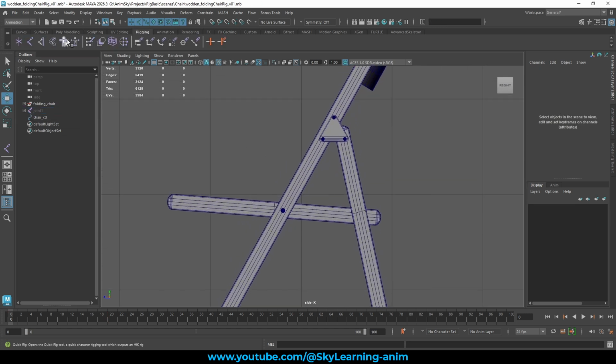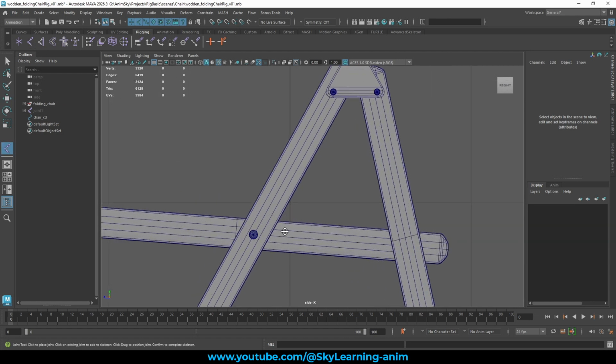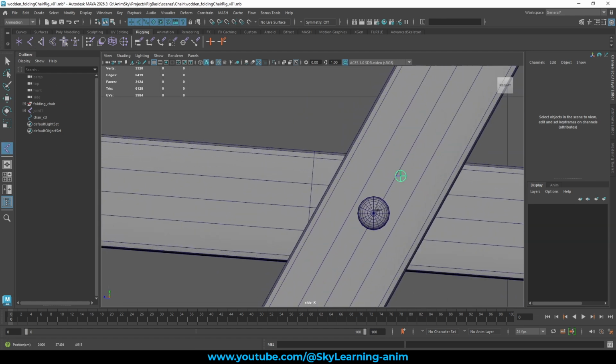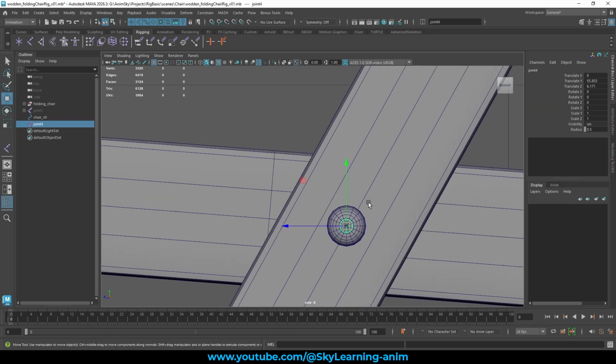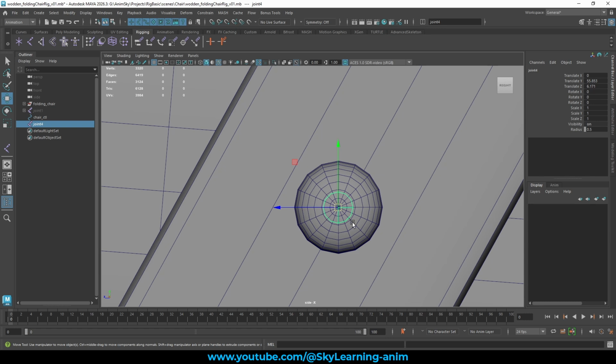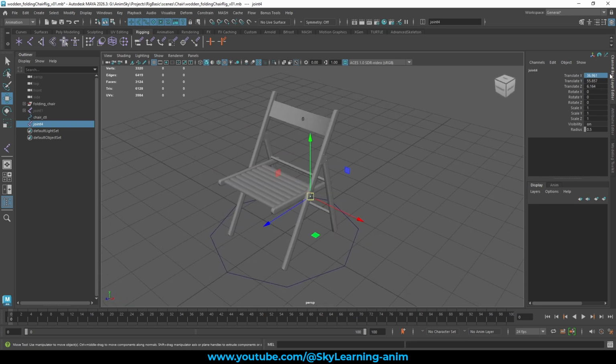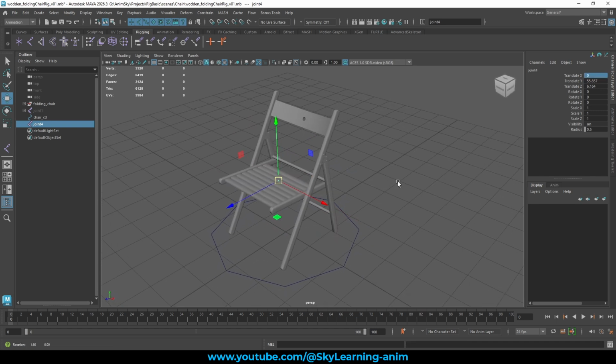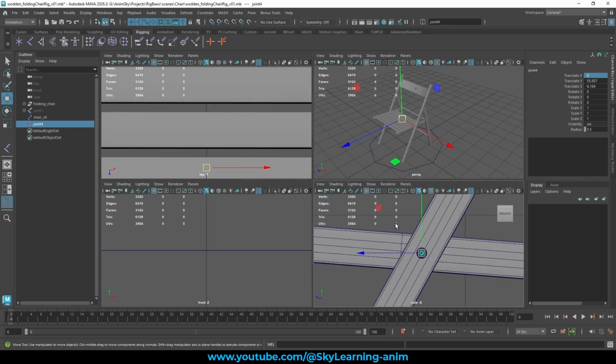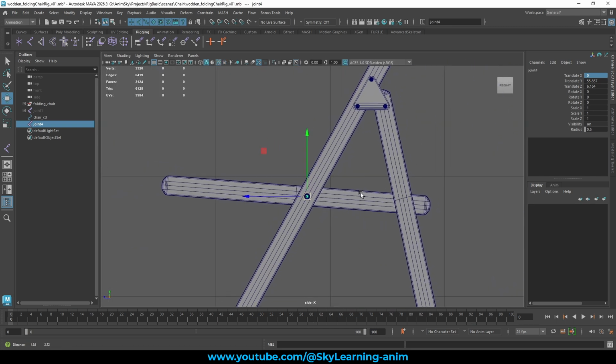Okay, go to rigging, go to creation, joint creation, zoom in and try to go to the center. If not, just like this and select this. It should be Y and Z. If you still got an X value, make the X value 0. What happens is it will go to the center. Right now it was snapped over here, but I want it at the center of the grid. So just make the X value center. All right. So this one joint is ready.